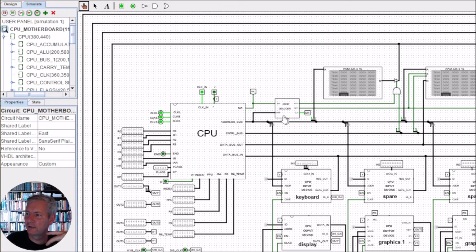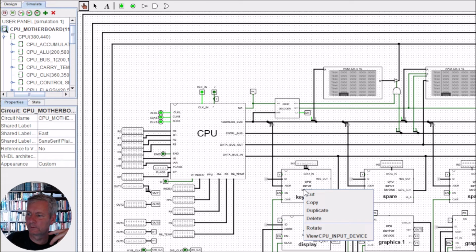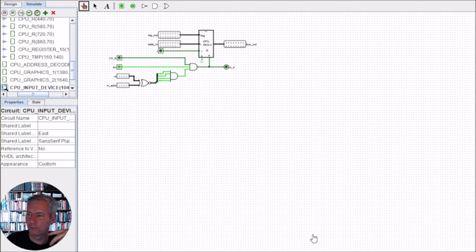So we can see the address that's going to come in here is FFF0. In this instance, the address decoder hasn't chosen the RAM or the ROM. The address decoder has said, well, we're actually going to be using one of the I/O devices. So this has gone high, the enable's gone high. Now the I/O device it's actually chosen will be the keyboard. So if you get into the keyboard and have a little look, you'll see here that the value is 0, so this has gone high.